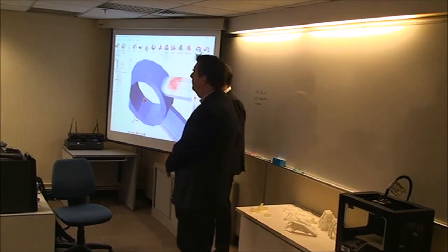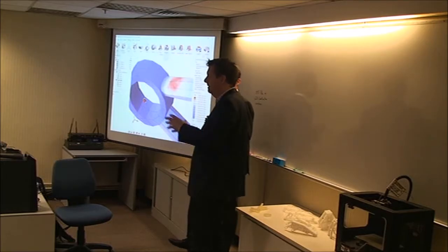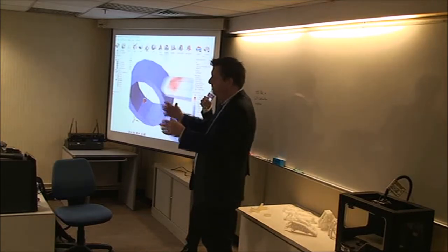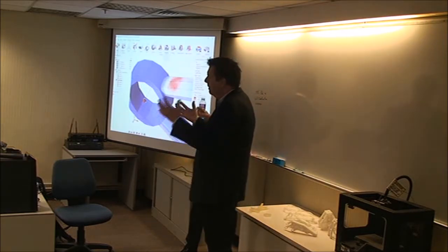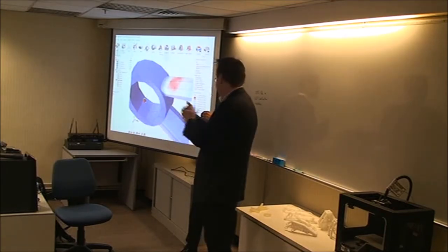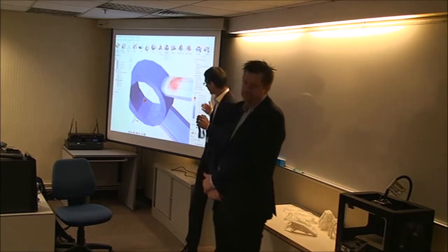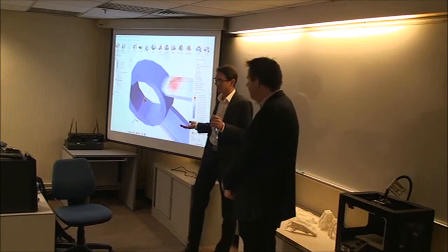How about the dimensions? It's no different for 3D printing than traditional methods. My master's was in cast rolling wheels. So we would X-ray every 50th wheel, just to check. You do load testing? Yep. Every wheel is visually inspected, every 100th wheel was X-rayed, every 1000th wheel went onto a test rig, something like that. Sampling. And there are some parts in the automotive or aerospace industry where you have 100% testing.